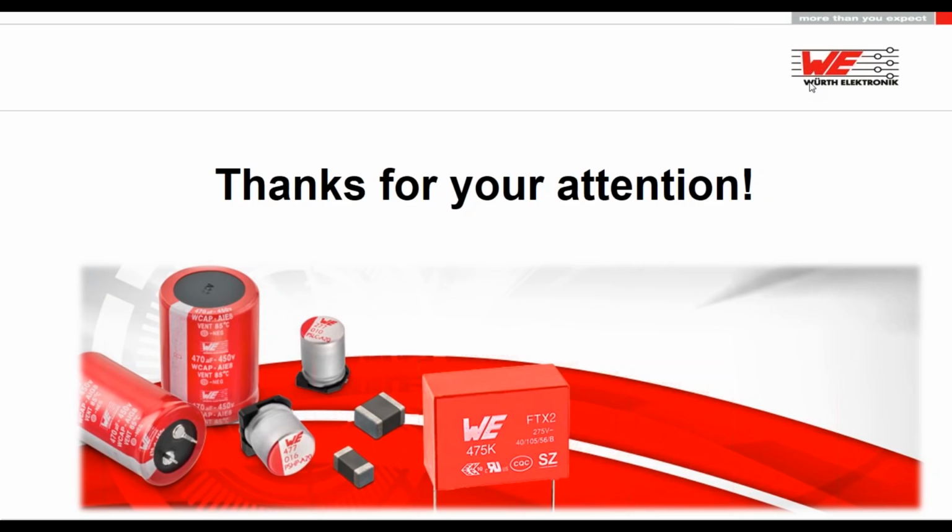Also, there's a question: what is the dry-out behavior for the electrolytics? For the dry-out behavior, what does it mean? An electrolytic capacitor is not 100% sealed, so you have just a rubber sealant on the bottom side, which is beaded with an aluminum can, and due to the fact that the rubber sealant is not 100% closing the cap, you have a certain interchange from outside to inside and from inside to outside, and this can result in dry out of electrolyte.